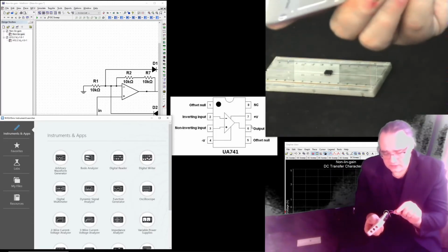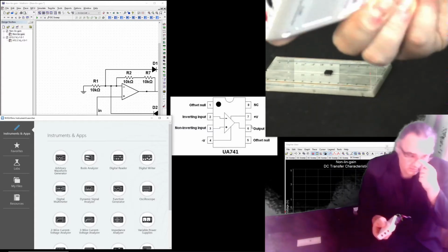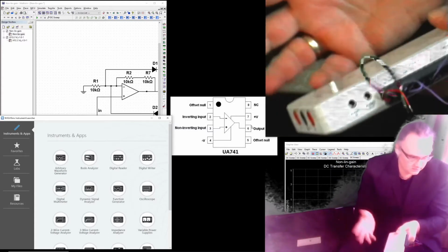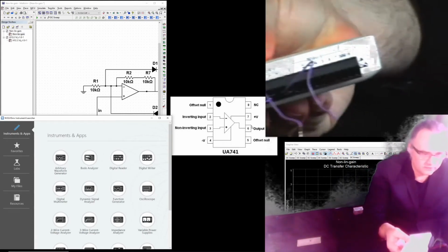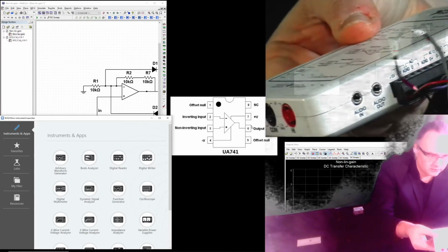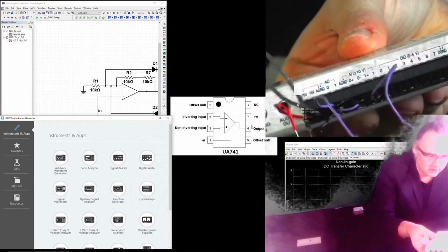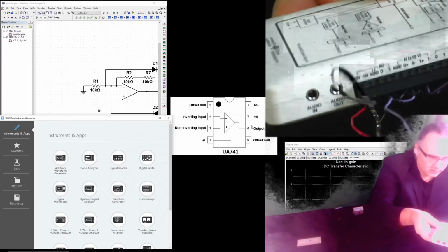And then I will use the other analog input 1 plus to measure my single-ended signal which I want to measure. So this is the configuration in the MyDAQ. You can pause the video and take a look exactly at my configurations. I hope that it is clear.